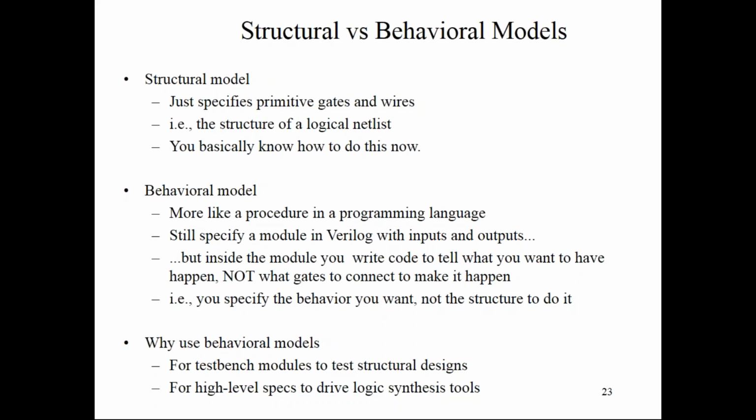For test cases, for example, if I want to generate test vectors for more than 50 inputs, I use a for statement: for i equal to 0, i less than 50, i equal to i plus 1, then A of i equal to %i. Likewise, I describe the test cases for the logical model we have designed.